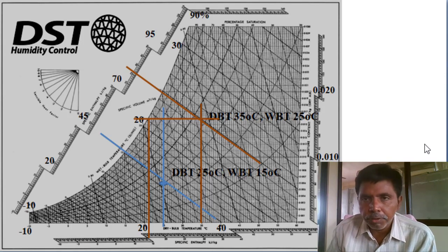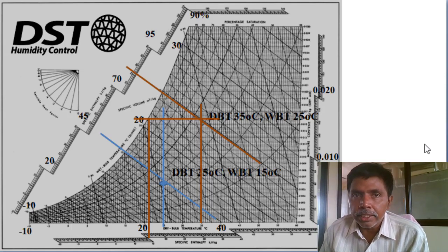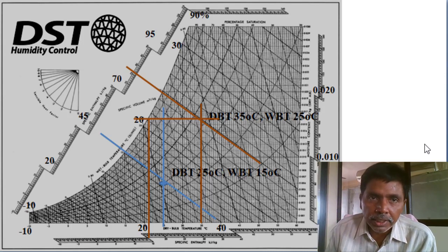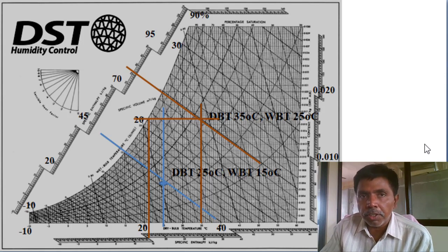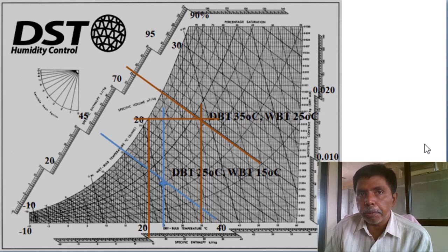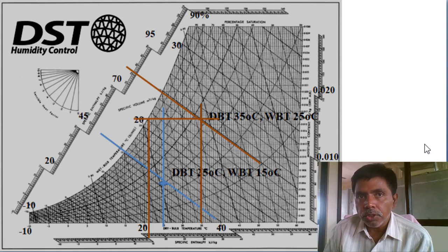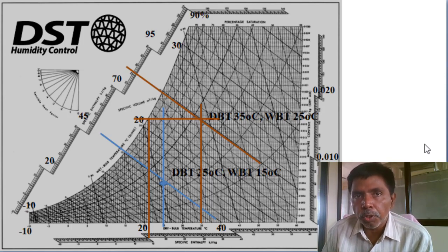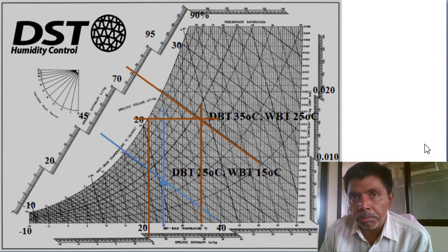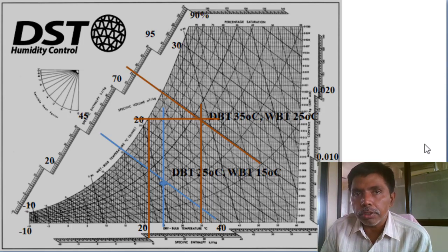But the duct area is fixed. That's why we adjust the velocity of the air, increasing and decreasing it. If there are heavy workshops, the velocity of the air is increased. For general office work, we reduce the velocity of the air. Because ultimately, while designing the air conditioning system, low maintenance cost is most important. We want to drastically reduce operation and maintenance cost. We want to reduce electrical bills. So we maintain these three parameters in an optimized manner to achieve human comfort.